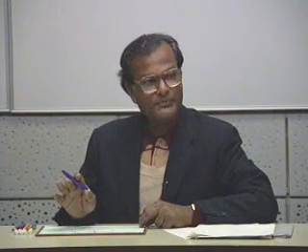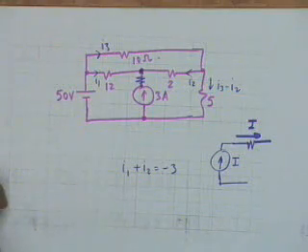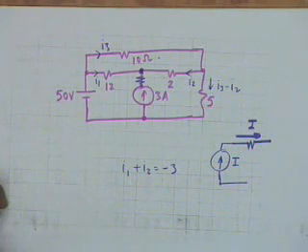So if there is a resistance in series, there is no change in the KCL equation at this node. Even then you cannot write a KVL equation, because you can find this drop, but you don't know what the drop across the current generator is. Any other question? Okay.